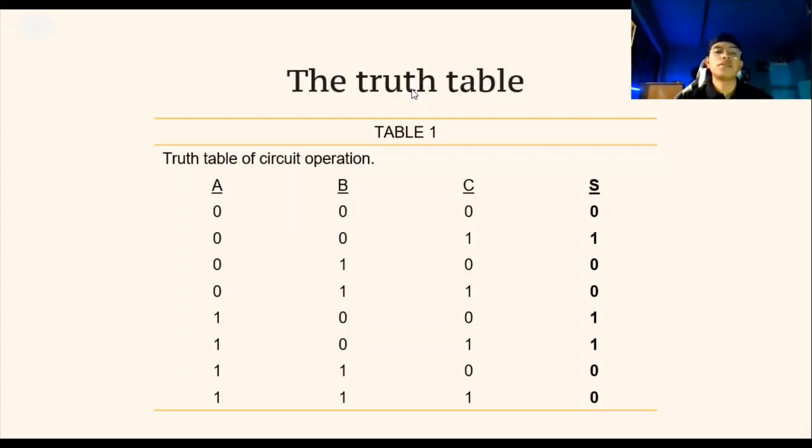When the stop button is at a high level and the other two buttons are in a low state, the output is 0. The circuit remains open because the push buttons are normally closed, and when pressed, it opens the circuit.